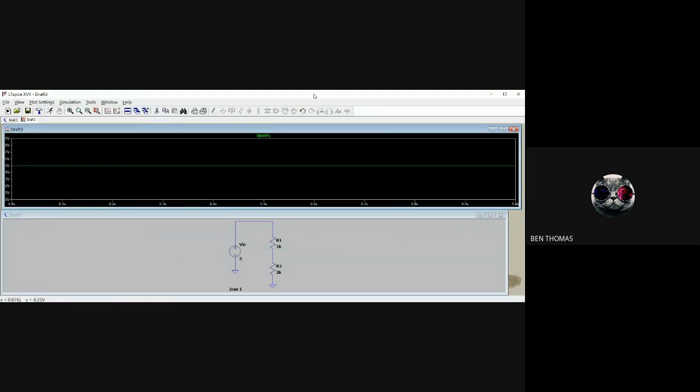Any doubts? Once again about that tick, can you explain the tick part? What the tick part means is on how many units the division should be. Now it's 1 volt, 2 volt, 3 volt, right? That's the scale. Tick actually means the scale of the y-axis. Let me change it to 2 volt. Then 0, 2, 4, 6, 8. That's what it changes, the scale of the graph, the scale of the y-axis. That's the thing you can change.